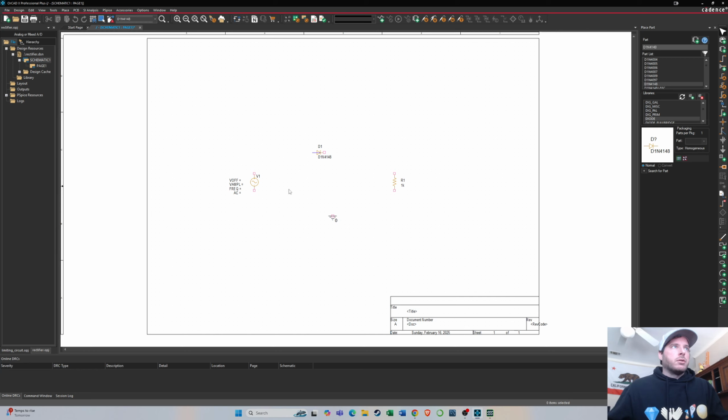We're going to start by clicking on the background again and pressing W. If you want to create a bend in the wire, you can click. That'll keep that part of the wire there. And then click again once you see that red circle pop up. That means you're connected. Click down here so it keeps the wire down there. Click. I'm not sure what this red dot is here, so I'm just going to redo this real quick. That's better. And then finally connect our ground.